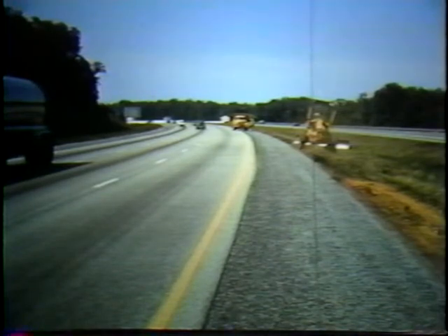Grass is another hazard to the shoulder edge. It can encroach on the shoulder surface, encouraging edge raveling and reducing the effective shoulder width. Drivers perceive the shoulder to be narrow, can't see glass and debris in the weeds, and will not pull completely over onto the narrowed shoulders.